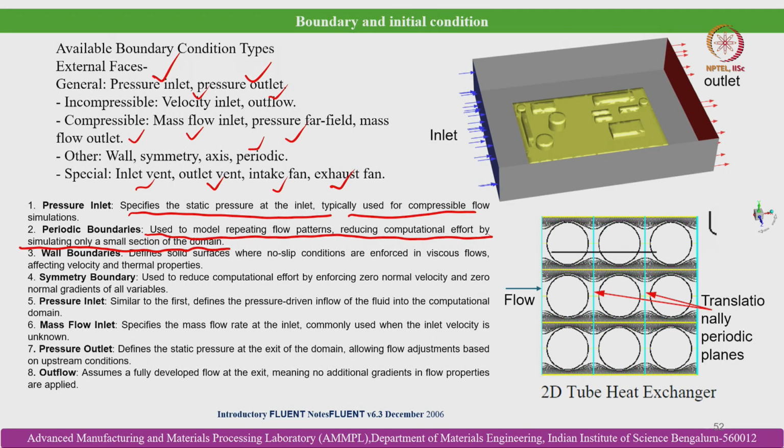Rather, it can be effectively solved for a small domain within the larger domain of the casting solidification problem in hand, and thereby we can estimate the pressure, velocity, and also the volume fraction of the secondary phase that is evolving from the primary phase, and what will be the viscosity due to the solidification that is occurring.